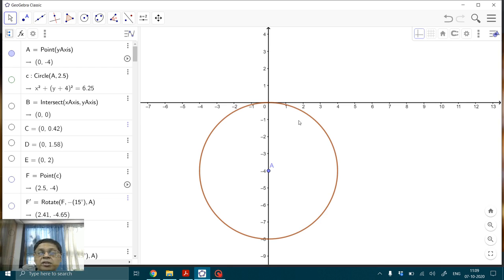So what we do is, in order to do the construction, before we draw various things, I'm first going to draw what is called an offset circle. So this is drawn with the cam center and the radius equal to the offset E. So this is 25 millimeters. So this is a circle that is drawn with a radius of 25 millimeters, the offset circle. Now remember that the translating axis is out here, tangent to this offset circle. So it is actually going back and forth here.